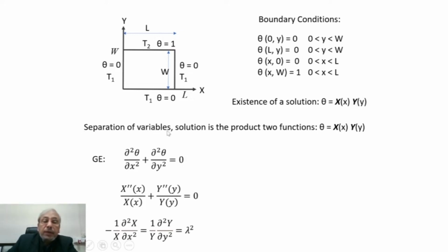So we will apply separation of variables. In this technique, the solution is the product of two functions, uppercase X as a function of x and uppercase Y as a function of y, and the product of these two functions will give theta. The product of uppercase X and Y will define the final distribution of theta.